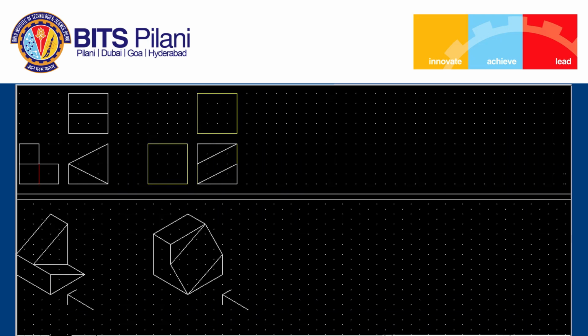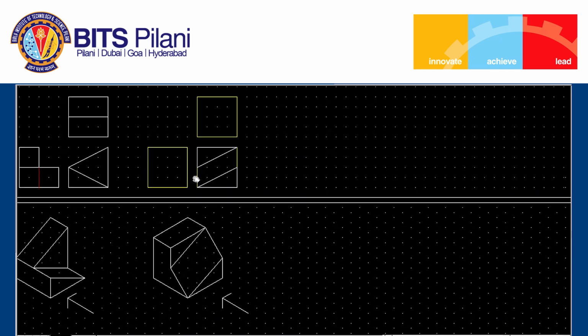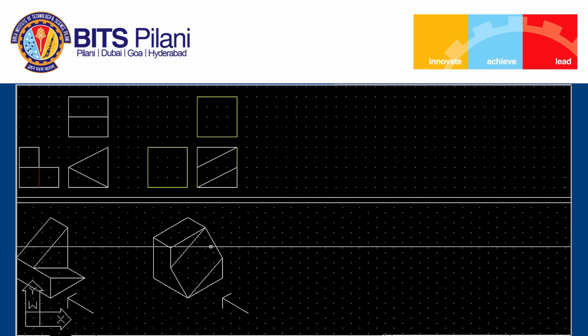Now if you see this principal surface, it will fall into a line view, and this principal surface will also fall into a line view. So, I have to show a complete line here and then try to satisfy the given skew surface. This corner I already have here, the second corner I got here, the third corner is seen here and the fourth corner is seen here. I join all the corners, and the skew surface will be satisfied.